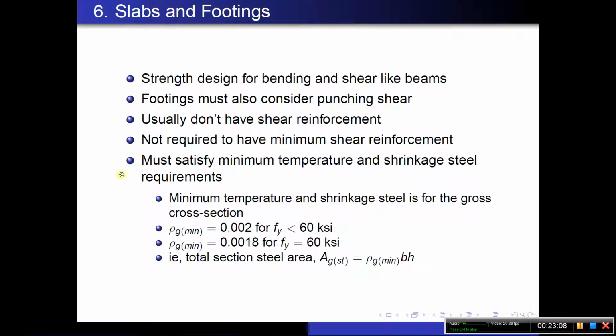So you are not required to have minimum shear reinforcement. The other thing is that when we were learning about beams, we said that there were minimum steel ratio requirements for beams. And those minimums do not apply to slabs and footings.